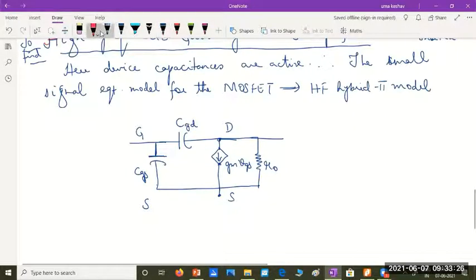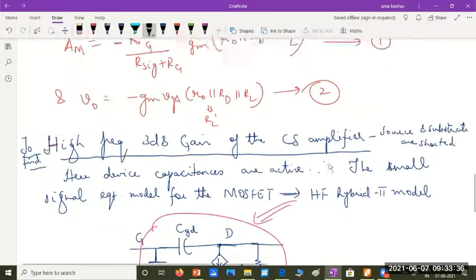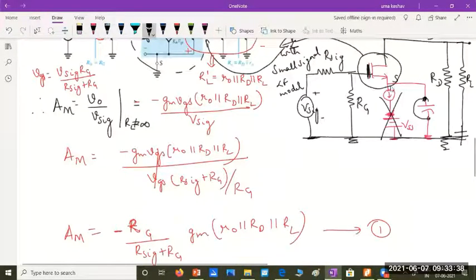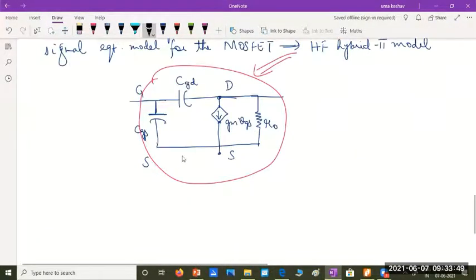Okay, so now this is the replacement for the MOSFET, the high frequency model. Now you bring the other elements from the AC equivalent circuit. I've just replaced the MOSFET with a different model. That's all. Remaining elements, you just bring as before. What should I write on the input side? First thing, the source should be grounded.